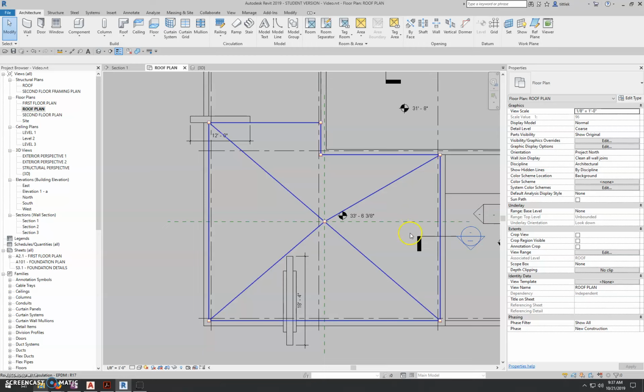And if we multiply that by 0.25, which is a quarter inch per foot, we get roughly 5.8 inches. We're going to round that up to 6 inches. Again, you can be higher than quarter inch per foot, but you can't be lower. So again, we don't have to get exact here. We just need some representation that's close enough for the tapered insulation.